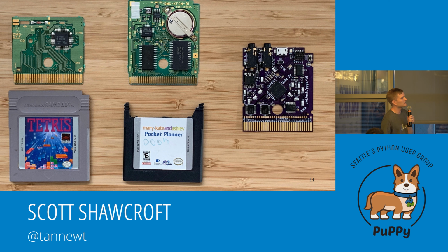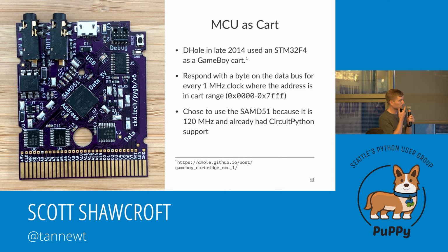And then the cart on the right is the cart that I designed, and we'll go into the way that works. Basically, we have a microcontroller in the middle there that is pretending to be memory. The Game Boy says, give me the data at this address, and we say, oh, I'll have this data. We don't really care. We'll go into more details, but basically, at a 1 megahertz rate, we have to give it data to do something. It's not too bad. The microcontroller on here is 120 megahertz, so theoretically, we have 120 instructions to do something in between.